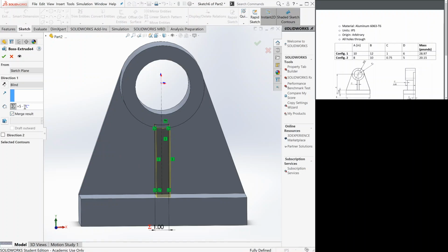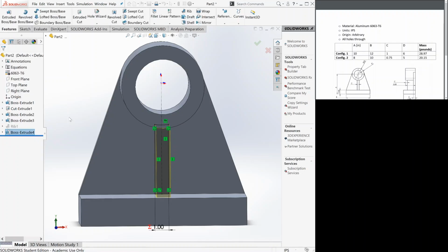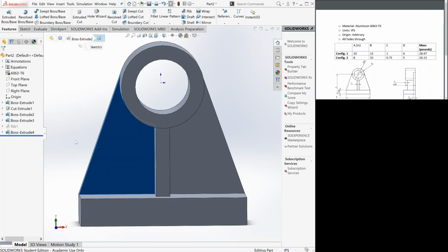So you're gonna go back here after minus parentheses space 2 space times space, and then end the parentheses after your global variable C. Okay, so this way we take into account the thickness of the back plate we extruded from. Perfect, there we go. The exact same results. So as you can see, there's thousands, hundreds of ways to draw the exact same thing. So I'm just giving you one simple way to do it.